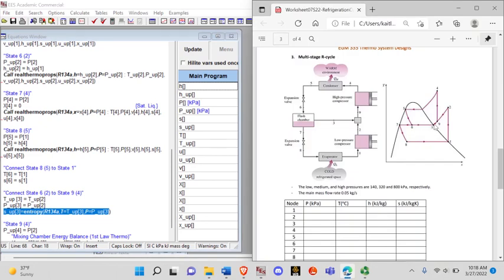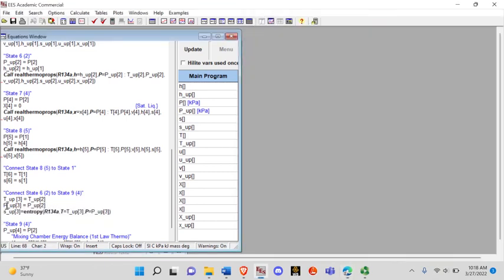Okay, so we're going to use quality because this is just basic thermodynamics. This is their constant pressure line. So here we specify temperature and pressure, but when the working fluid is changing from saturated liquid to sat vapor, it can't tell what the quality is based on these values, and it can't tell the entropy. The entropy could be any range of these values within this. So we need to denote that there's a quality of 1 because it's sat vapor. So I'm going to do x up 3, x up 2, and change this back to quality.